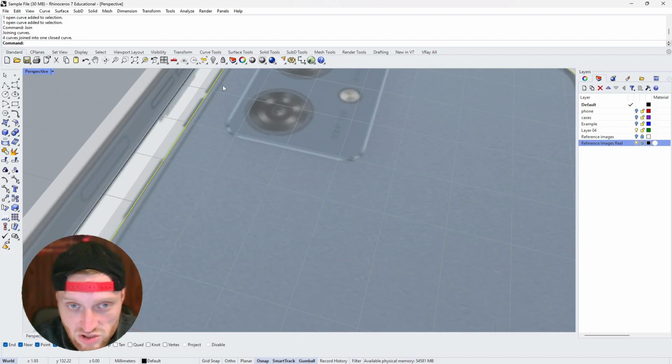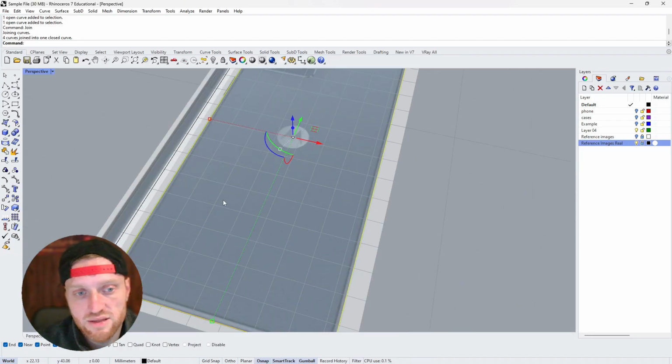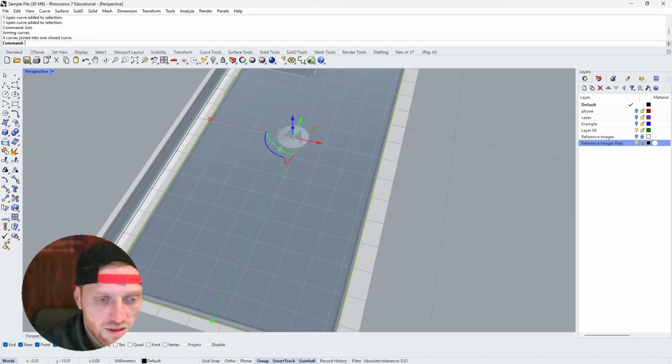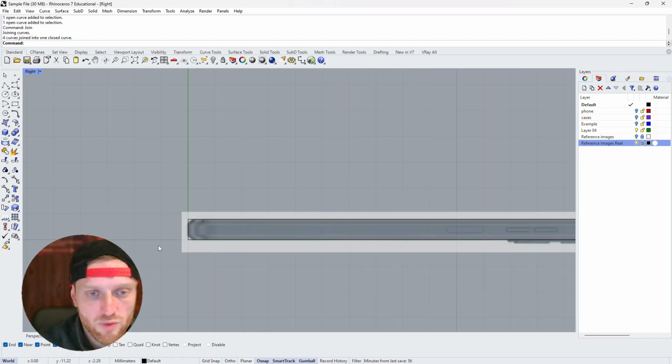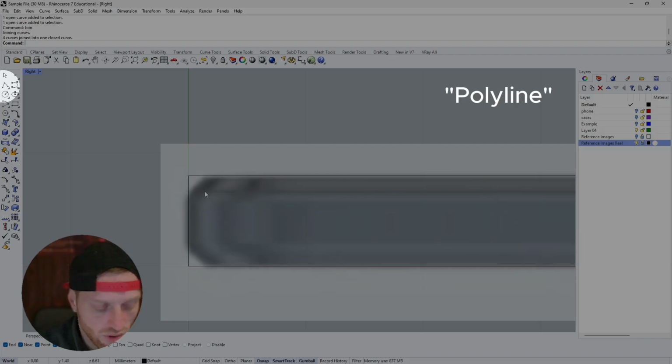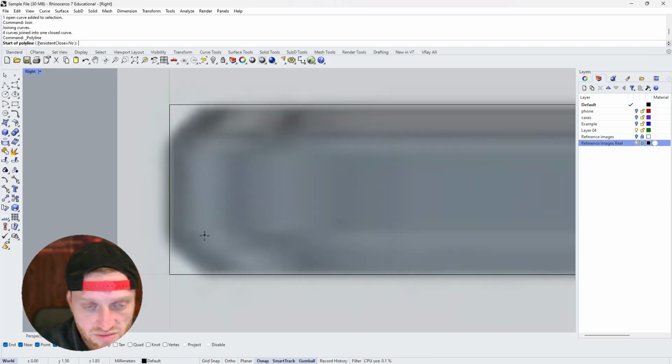And now there are basically two different approaches that we can go ahead with if we want to make our phone case. I show you first the way to do it with the sweep command, and then I show you how to do it with the extrusion and Boolean operations, right? So if you want to do a sweep, then we need a section of our phone case. So we just have to sketch it.